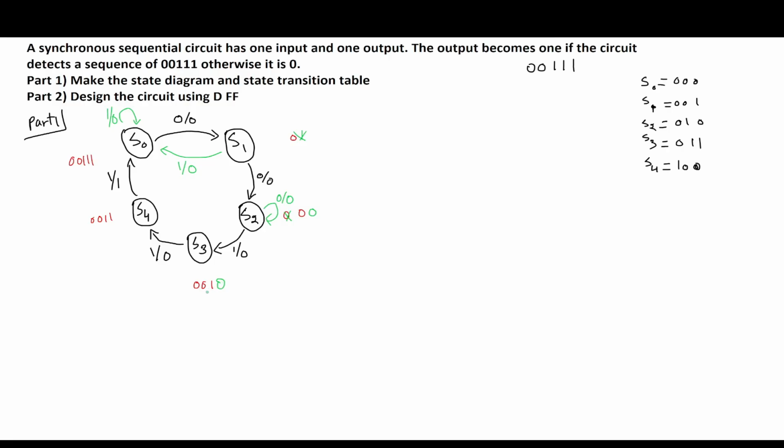So let's see what can we discard in the back here. If we discard 1, 0 here, we'll remain with 0, 1, 0. That doesn't correct our sequence. If we discard 0, 0, we'll be remaining with 1, 0. We cannot continue the correct sequence. So that means we need to discard all of these 3 and go back to S1. So we'll be left with 1, 0. So that means we can continue from S1 and still make the correct sequence, 0, 0, 1, 1, 1.